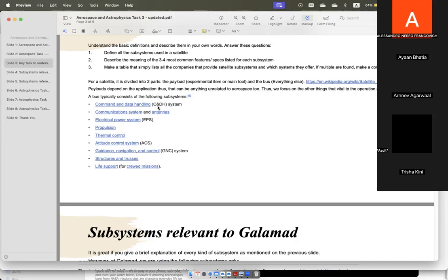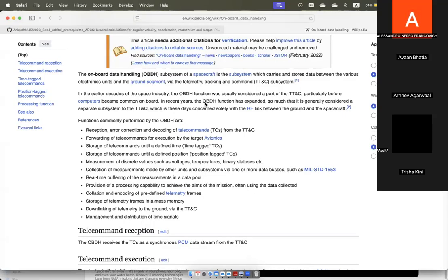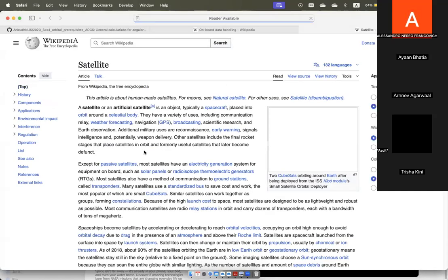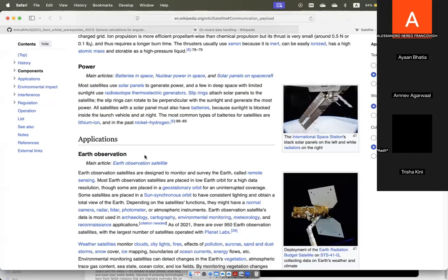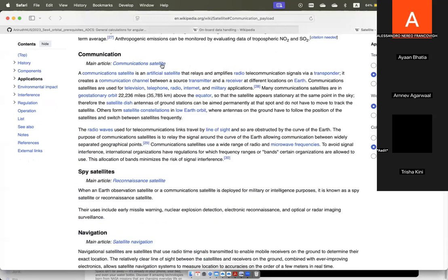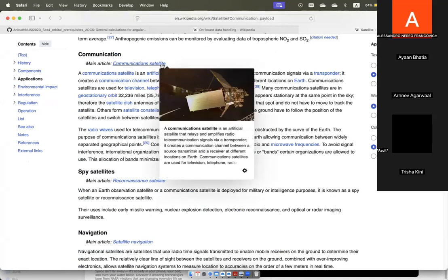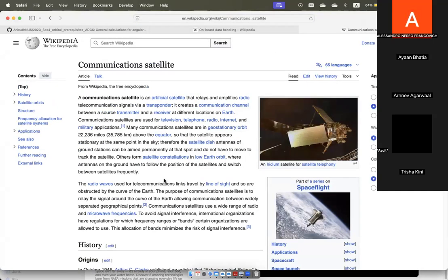Now, the communications subsystem itself depends on the frequency that you would want to transmit on. So in some cases, it can come as a communications payload. That is to say that the actual payload for your mission might be just the communications device itself. So this is actually the case in the current mission that we're building. Our own X-band transmitter is the payload.